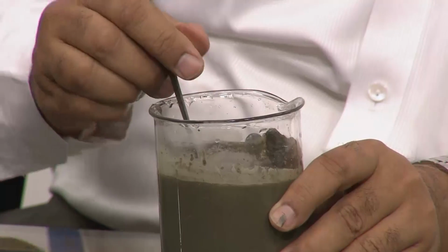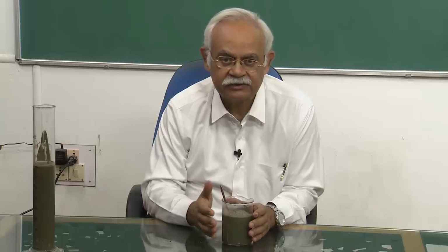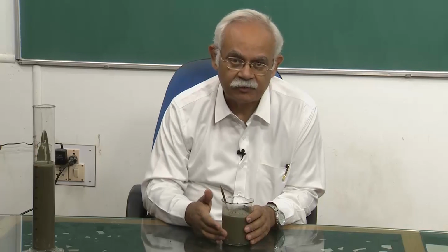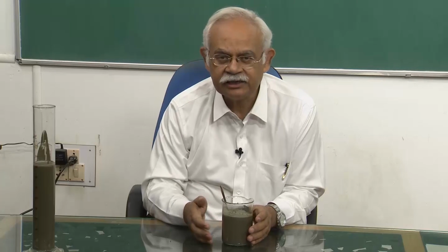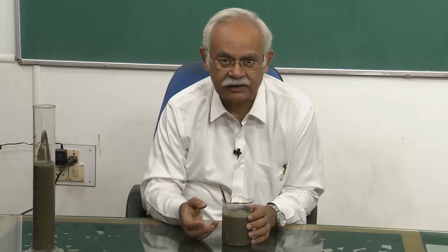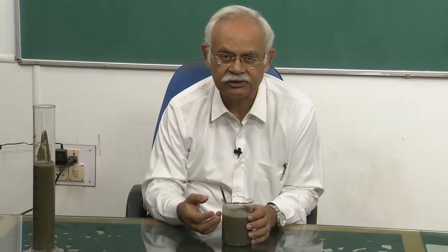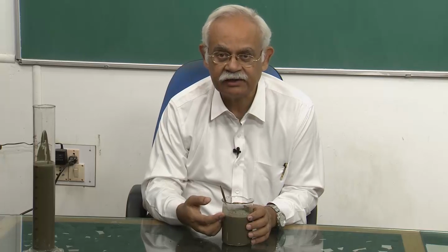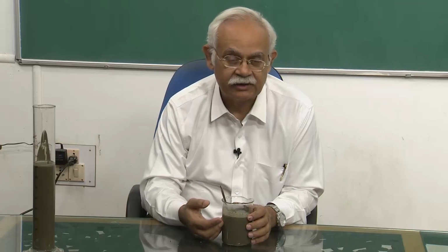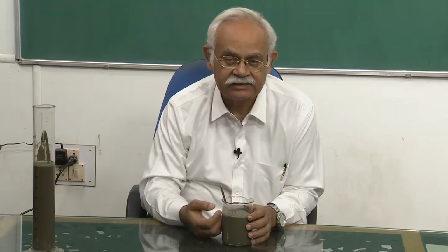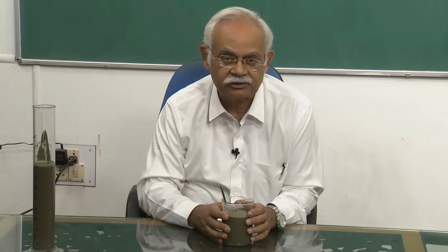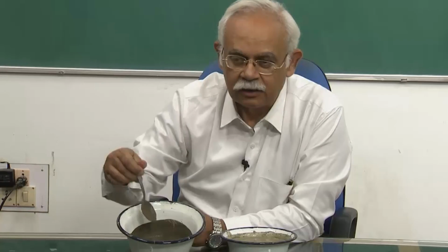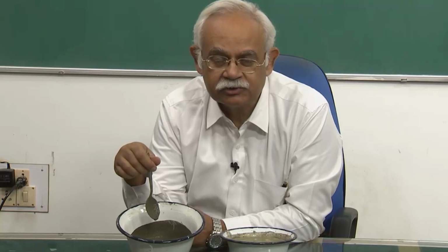Intuitively, it will be clear to you that the extent of this reduction in fluidity or any change in the properties of that paste would be related to the properties of the sand in terms of its fineness, water absorption and so on, and also the amount of sand that is added. So in this case, we have added 1890 grams of sand. So if we add more sand or less sand, the extent of modification that occurs to the properties of paste would be different.